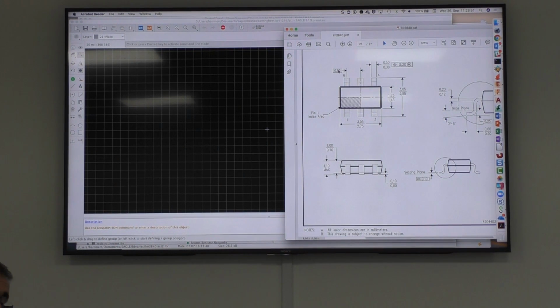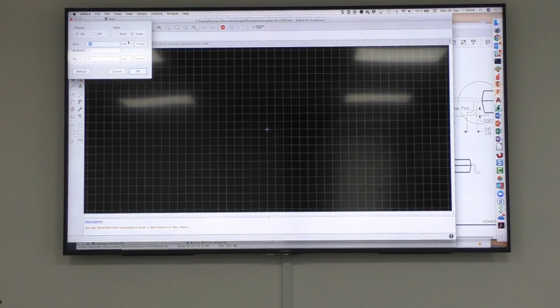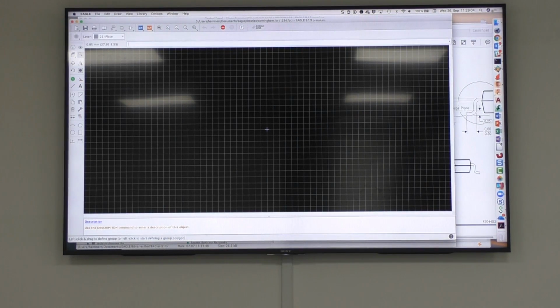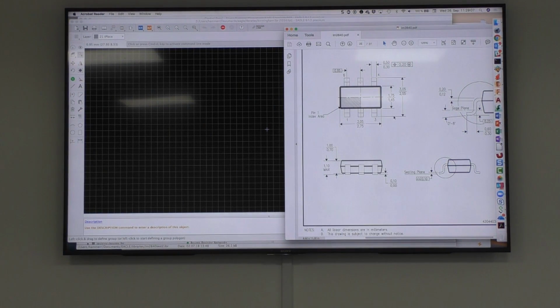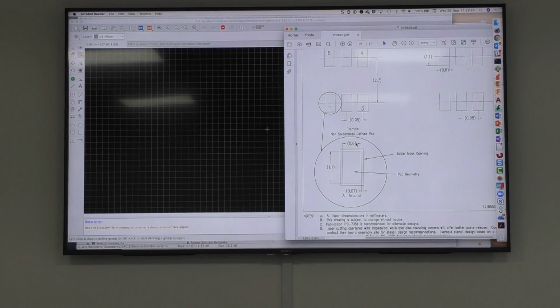The first step, I use this grid. So I go into my grid, set it to millimeter, makes sense here, and I use 0.95, I think it was, okay, now it's changed. Yeah, next step. Now I need a calculator. I could read the length of, what's the length of the SMDs? It's got the recommended footprint if you scroll down the page. Yeah, that's correct. There we have it, 0.6, 1.1. That's the size of my SMD I want to have.